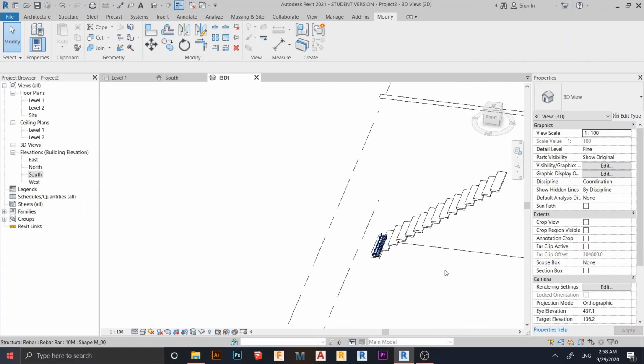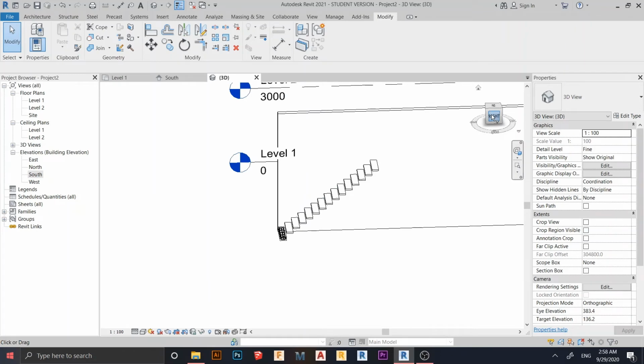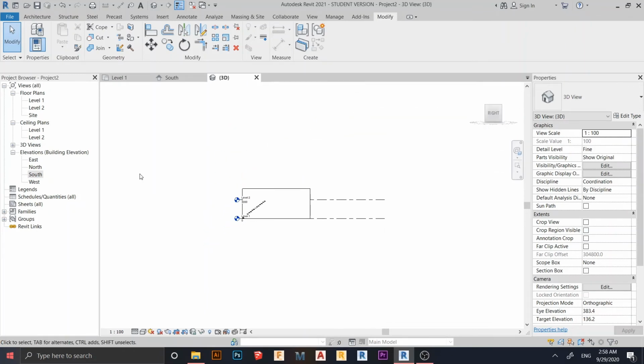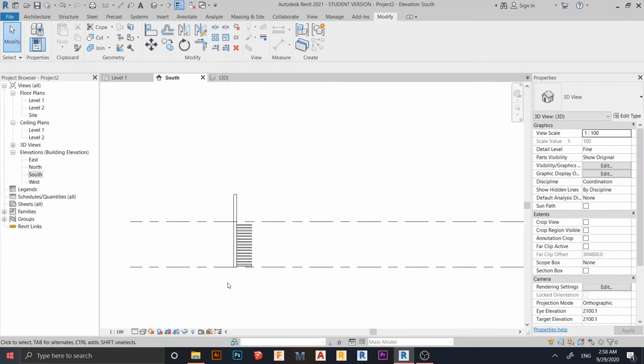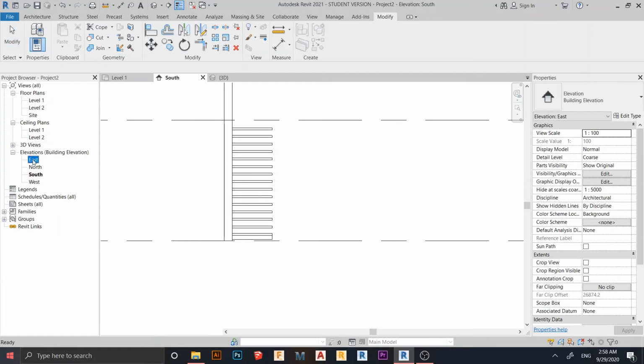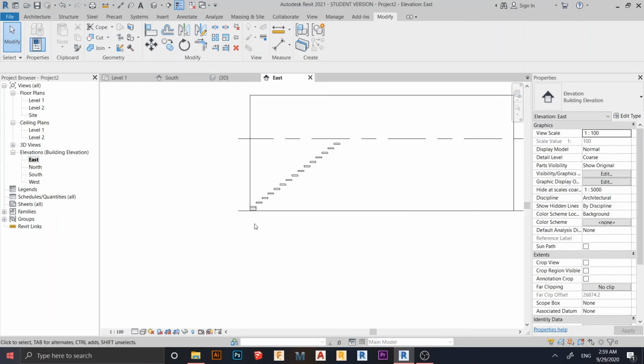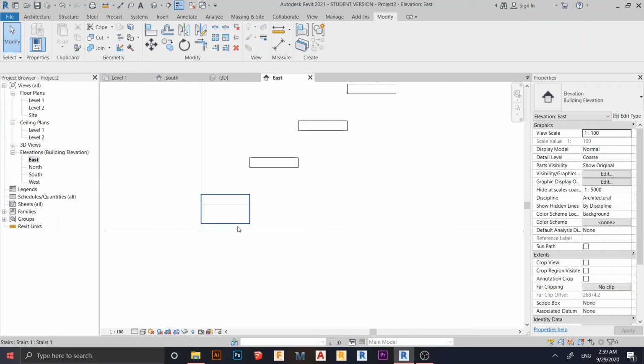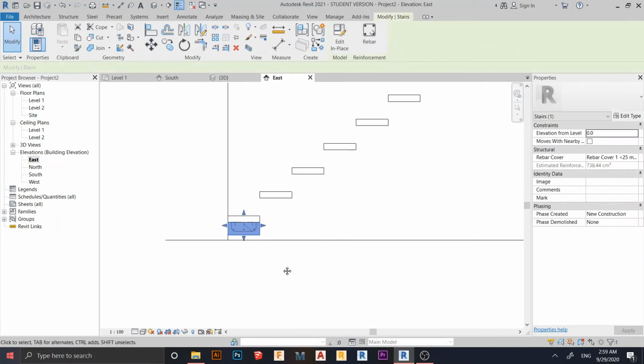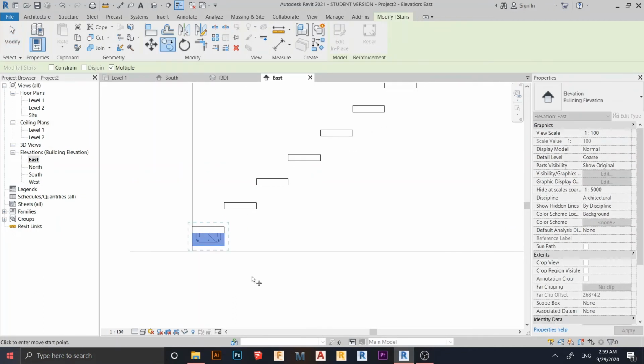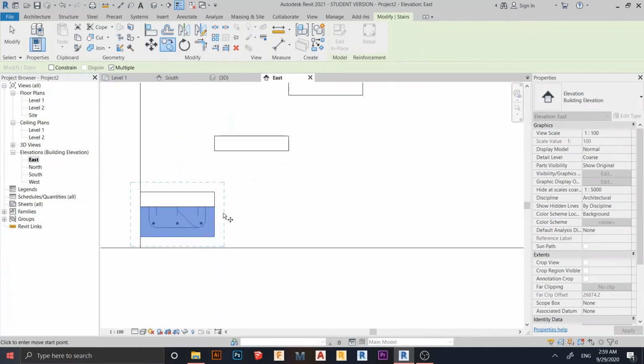So now it's time to copy to finish our tutorial. I just go to my elevation here. Select my new stair extrusion here, CO on my keyboard for copy. Make sure you take multiple selection. Start from the corner here, something like this.